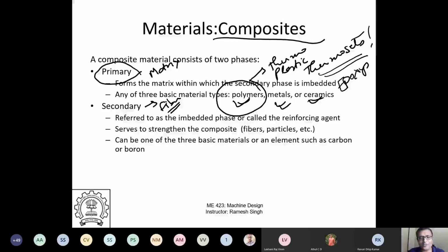So when you see most of the composites, you can lay the fiber and put epoxy, which will have an epoxy resin and a hardener. That's how you lay up layer by layer. There are two ways to do it. Either you do hand layup, or you can do automated layup. I'll actually show you some examples today of how the Boeing plane is made. So you'll get some feel for it.